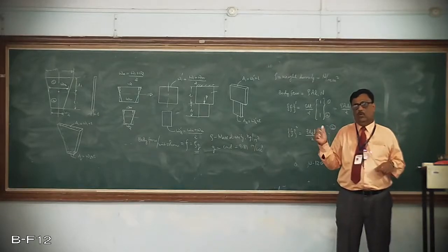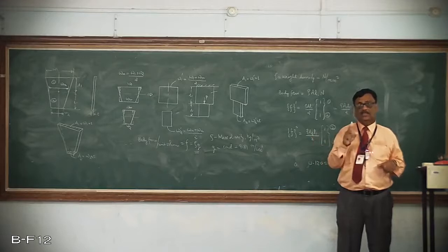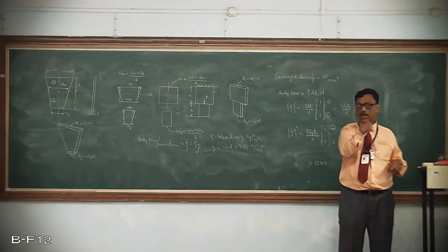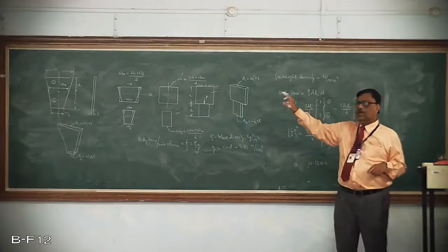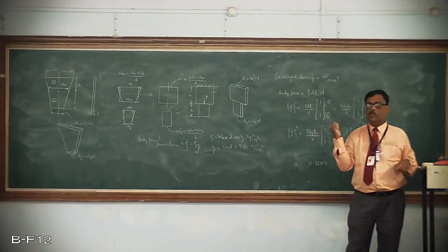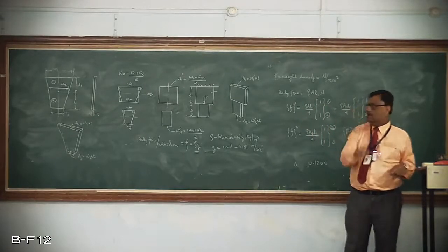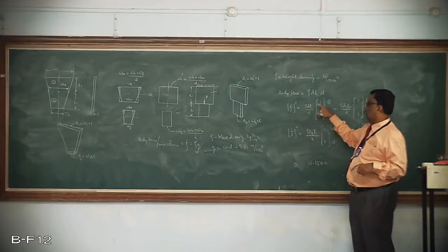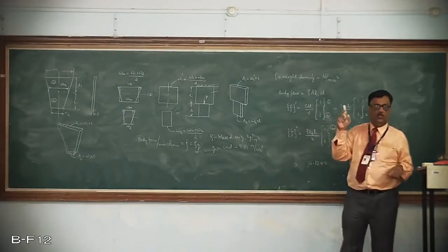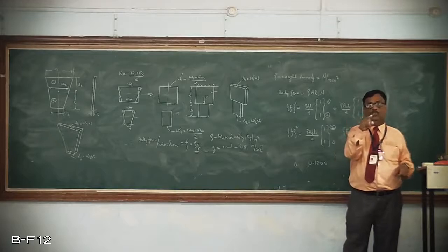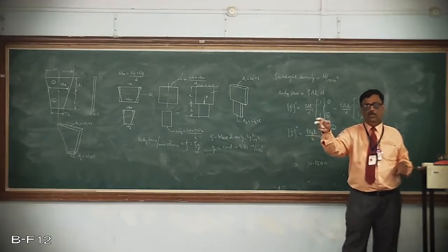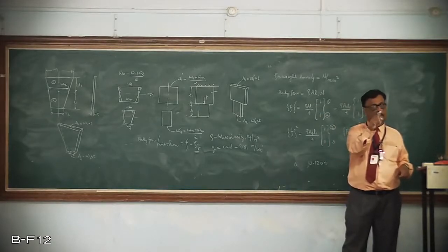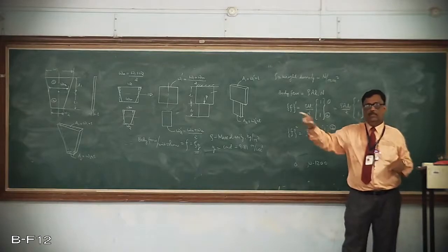The very interesting point you have to note in this problem is while finding the reactions. In the elimination approach, when we write minus F1, we generally say there is no force acting at node 1. But in this particular type of problem, node 1 also carries this much force, which is already acting due to self weight. So I cannot simply say minus 0. It is K11 Q1 plus K12 Q2 plus K13 Q3, bracket complete, minus F1, which is nothing but rho A1 L1 upon 2. That you have to consider. That will give me the correct reaction.